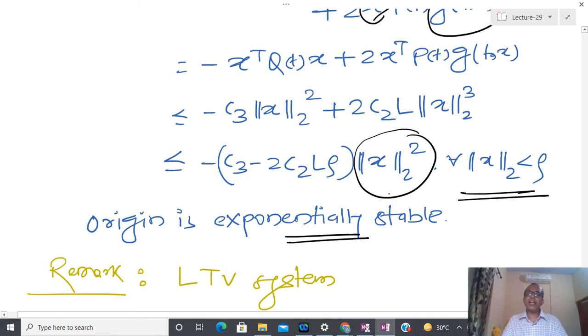Okay, up to here, if anyone has confusion, then please let me know. So you have to do the same kind of homework. Whenever we have a time varying system, an extra assumption comes into the picture. What kind of extra assumption? That whatever A(t) matrix, that should be continuous and bounded, that kind of assumption is required. Okay, after that, whatever P(t) matrix you are going to consider, P(t) positive definite symmetric matrix, that should also be continuous and bounded, and Q you will take continuous, symmetric and bounded, then it is possible to show that for a given A(t) there always exists a P(t).